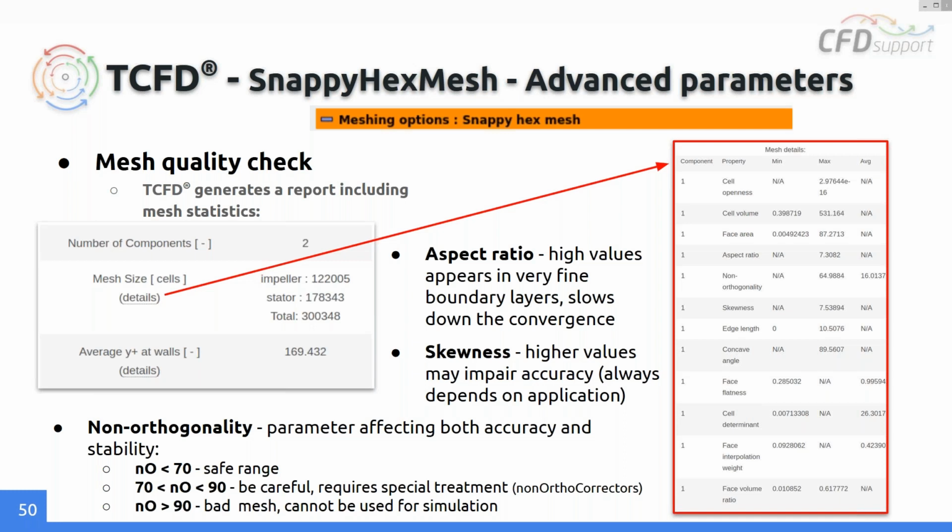You get this usually for the hexahedral structured mesh, and it doesn't affect the accuracy too much, but it affects convergence, for example, of the pressure equation solving. So you can see that the solver uses more iterations, which implies that the simulation takes more time to converge.